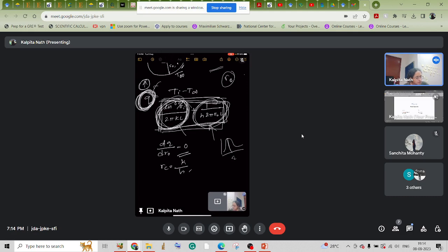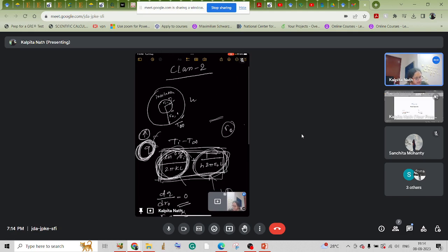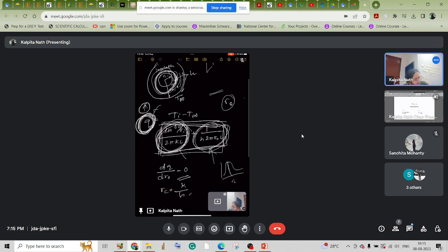How? So what is happening is that initially, when we add this insulation layer by layer, as this is not a plain wall, it is not uniform, its area keeps increasing as we keep adding insulation. So its conduction will decrease because of the insulation added, but as the surface area outside is increasing, the convection will increase.